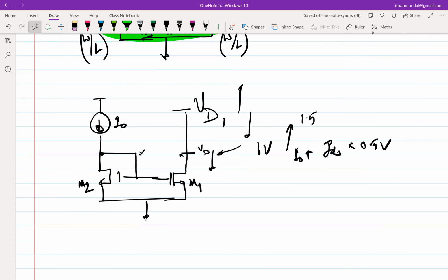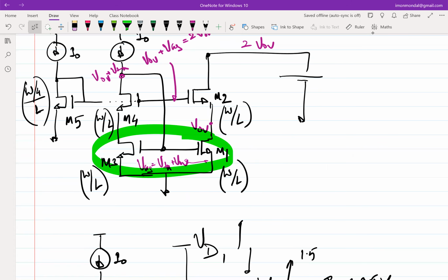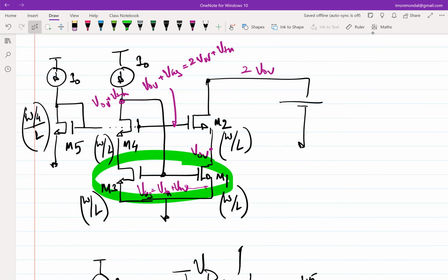in this case also? And so when we move on to another problem, we are dealing with wide swing current mirrors. Right. So we have developed that model to mitigate these effects, like matching. Correct. So in that case, we can neglect the effect of channel length modulation. You can neglect it if you are not bothered about it, but obviously in this case also, if you change the drain of M2, you will have some change, right? GDS is not 0 or RDS is not infinite.